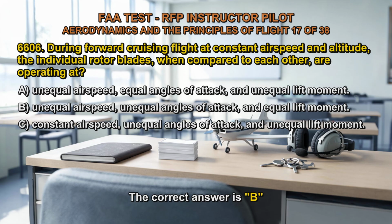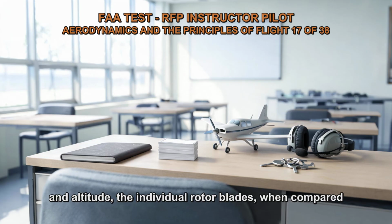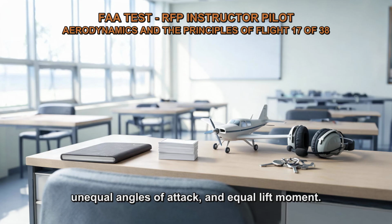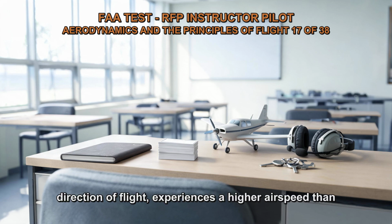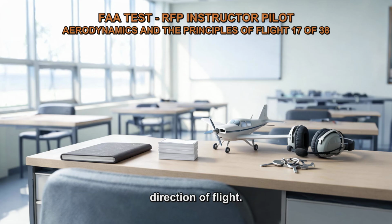The correct answer is B. During forward cruising flight at a constant airspeed and altitude, the individual rotor blades, when compared to each other, are operating at unequal airspeed, unequal angles of attack, and equal lift moment. Unequal airspeed: as the rotor disc rotates, each rotor blade experiences different airspeeds. The advancing blade, which is moving in the direction of flight, experiences a higher airspeed than the retreating blade, which is moving against the direction of flight.